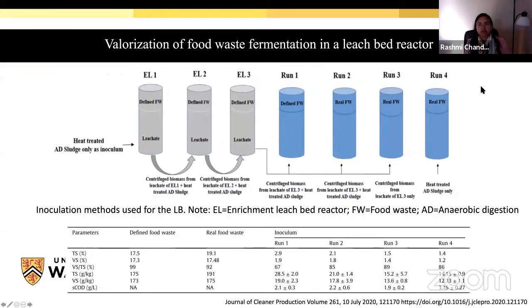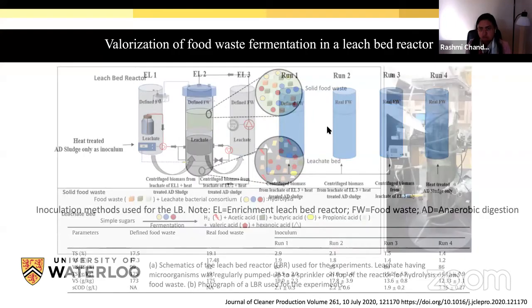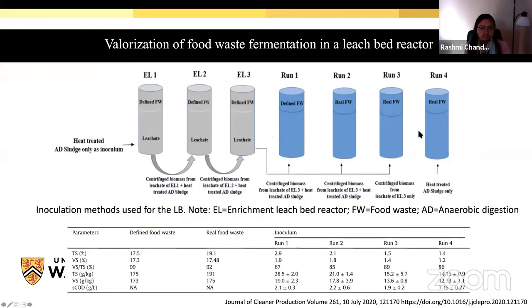So this is the way we feed the reactor. The first three cycles we go for the defined food waste, and the last three cycles we go with the real food waste. The TSS, VSS, all those wastewater treatment protocols we follow to quantify the soluble COD, total COD, TSS, VSS. I give the parameters here.